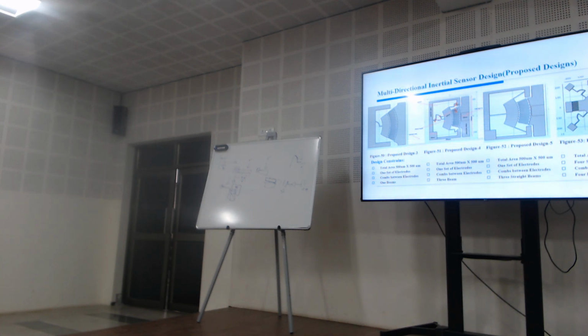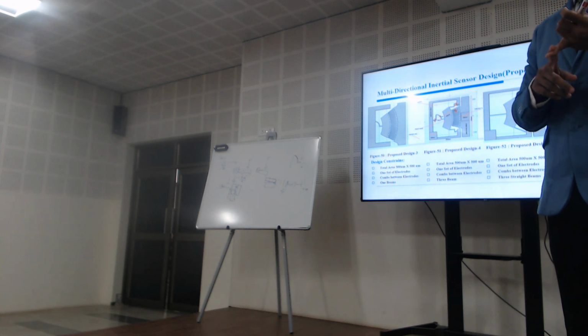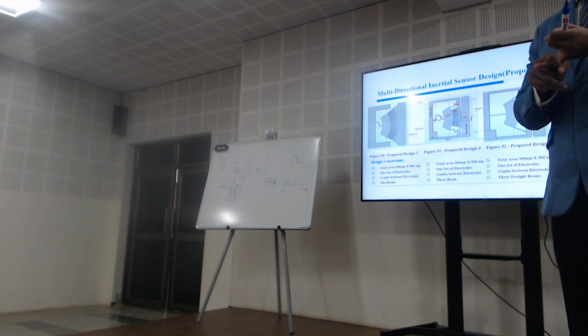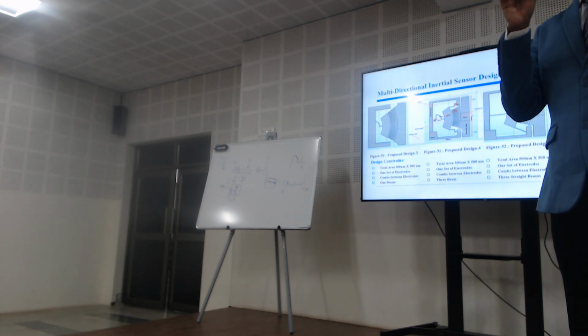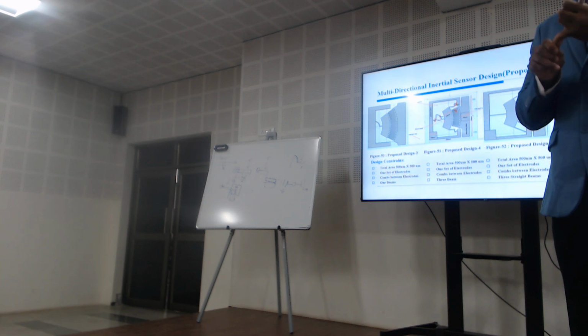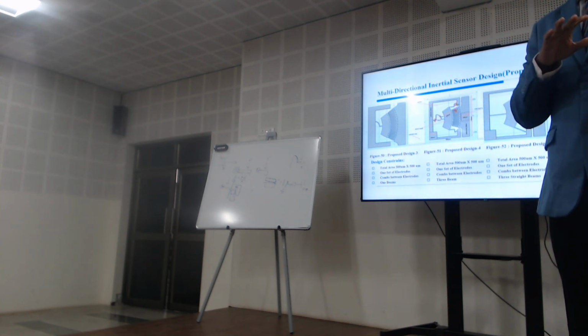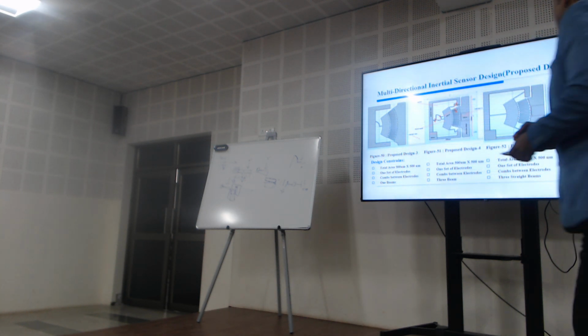The size of each is 500 by 500 micrometers only. Why I made these four sensors means I want to compare depending upon size, depending upon electrodes, depending upon the differential capacitance, how much sensitivity values are changing, how much spring constant is changing. All things I want to be compared. So that's why I started with four parallel designs at the same time. Right?